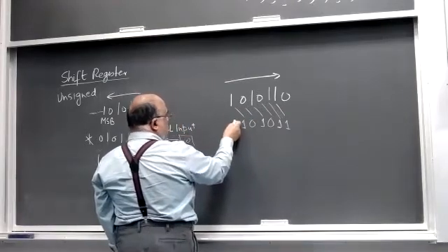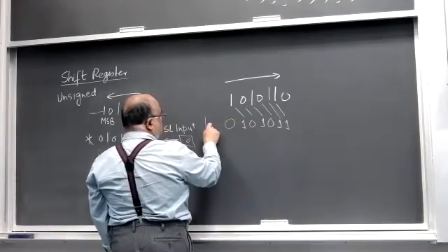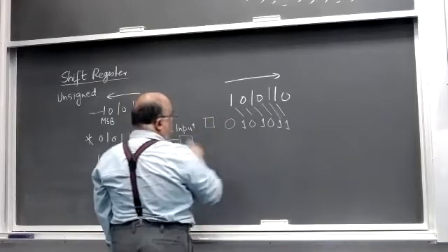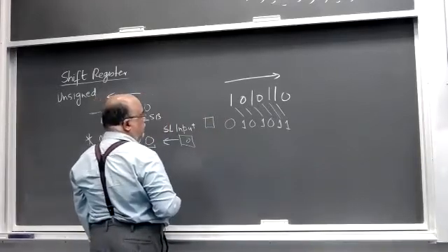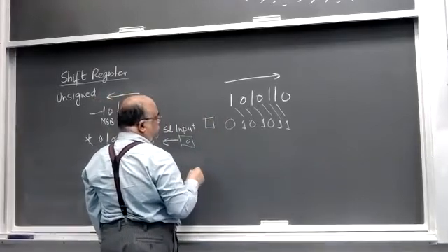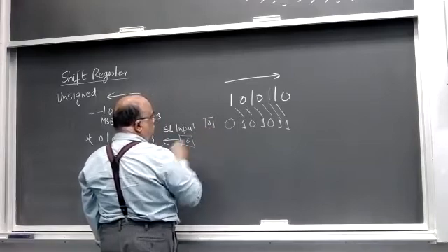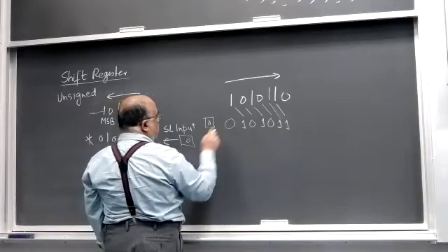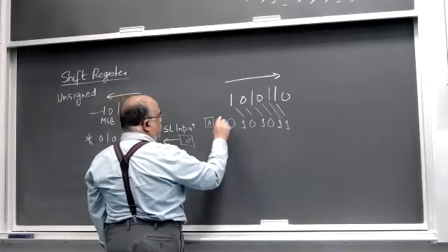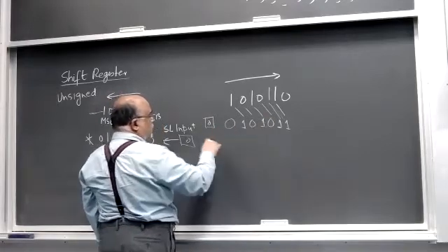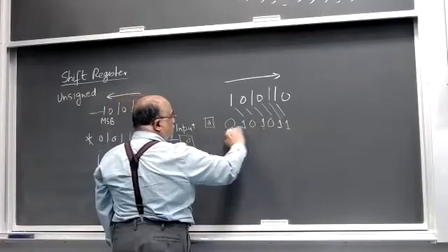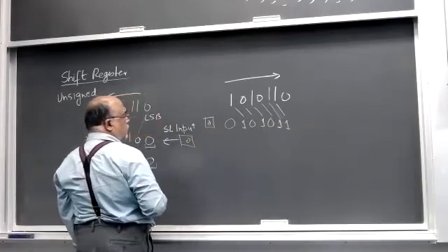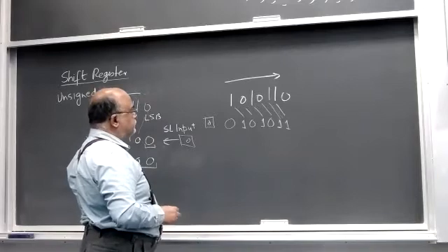What happens here depends on the IC. It depends on what value you want to shift in, 0 or 1. You can set that. There is a pin. Whatever you give on that pin will be shifted in. If it is 1, after all 8 clock cycles all the values will be 1 on an 8-bit register.